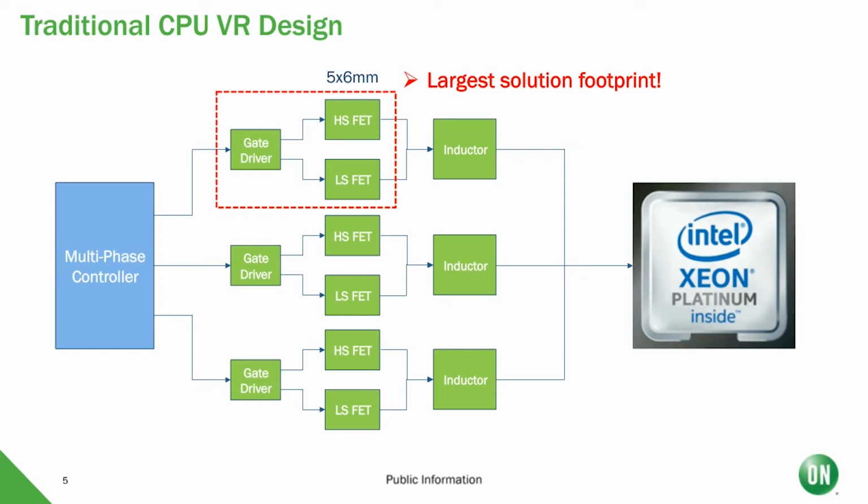So each FET comes with a breakdown voltage rating, so we definitely do not want to exceed that. By combining the different components into the same package, we're able to minimize the parasitics, inductance, and resistance inside the package, so that we can keep the switch node ringing small.